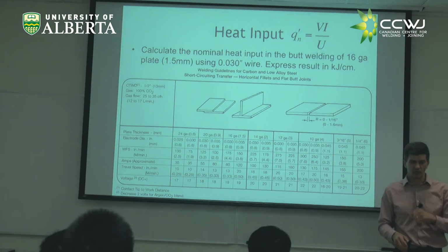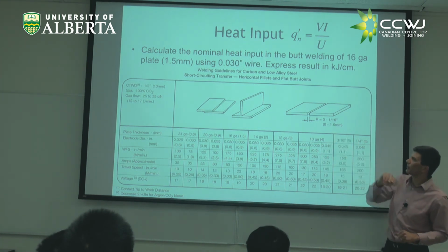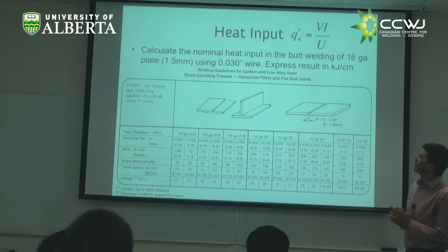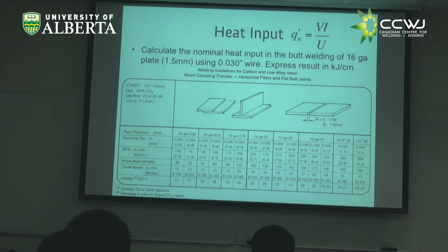I'd like to give you 3 minutes to go over this problem, right? What is the nominal heat input in this butt weld? We said voltage times current divided by velocity.